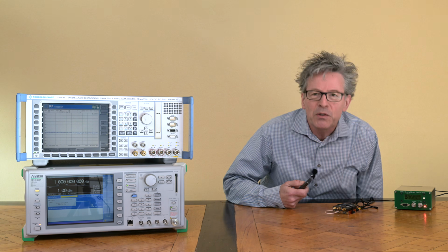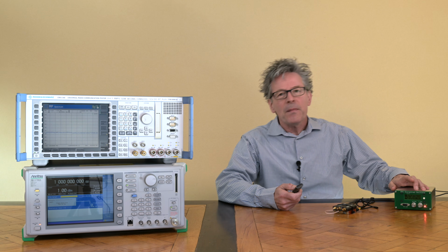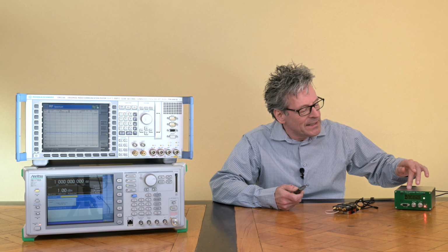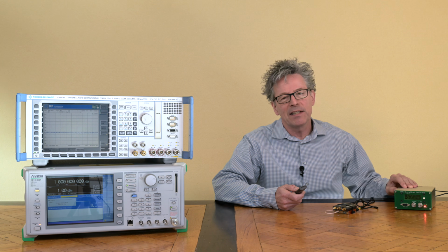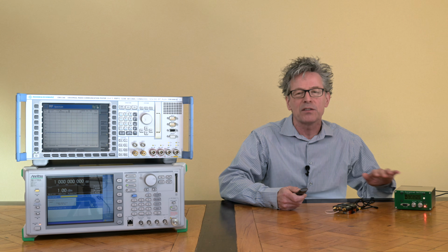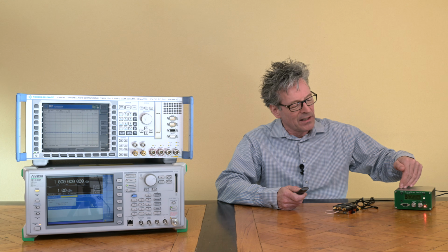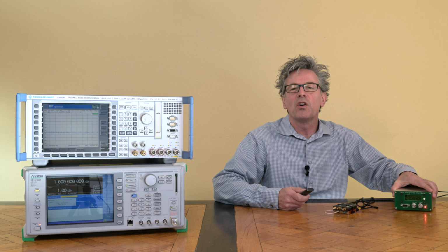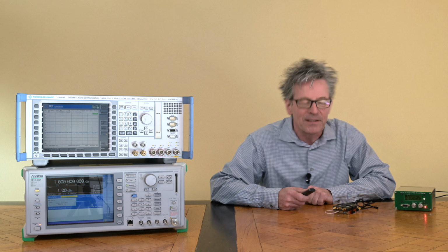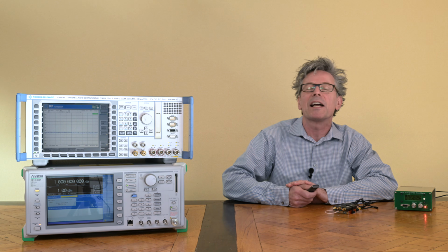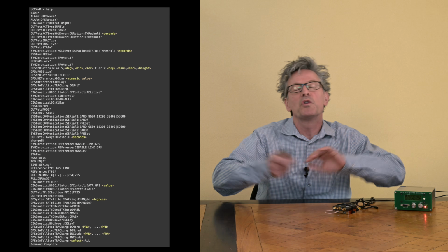But what's going on inside that unit is also kind of interesting, because like many units that are sold on eBay, the actual disciplined oscillator in here is not a new one, but a second-hand one. It comes from another device that was taken off the market or decommissioned, and eventually they bought this unit, put it in this box with a display, and gave it a new life. So where do these units really come from? Well, I found it out myself by connecting something to the serial port here, and you can use a bit of a language to do queries and control the whole device and read out all the values.